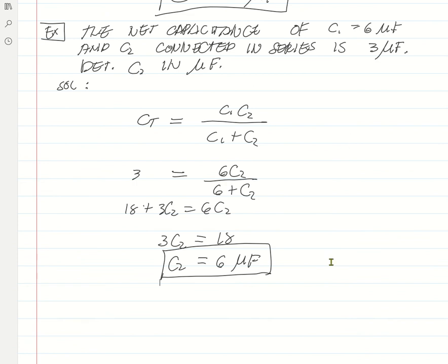So if you look at this 6 and 6, because they're connected in series, the capacitance will go down, and it's actually half of the two capacitances, which is 3 microfarad.